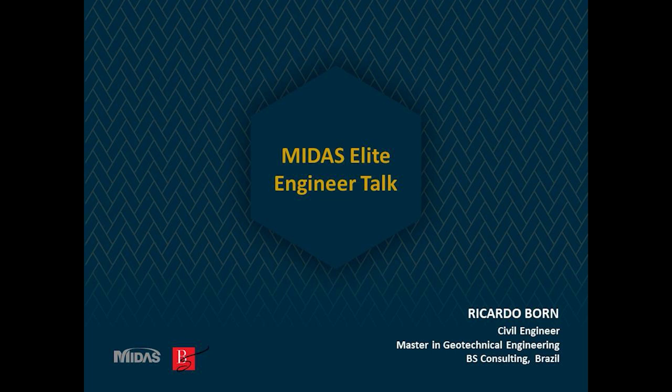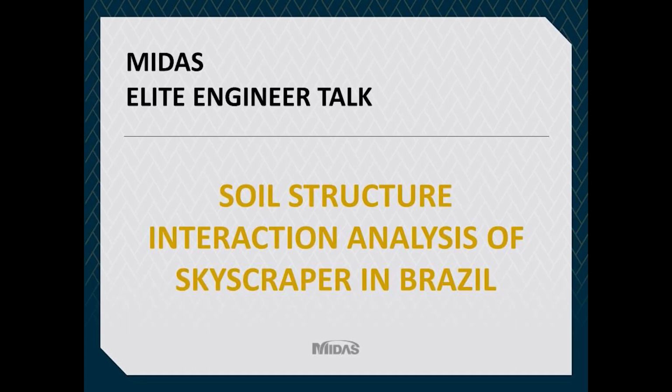So, along with a platform that enables this modeling, the soil properties might be modeled with the use of soil constitutive models. And MIDAS GTS NX allows this analysis to be done with all those prerequisites. So, this case presents a soil structure interaction of a skyscraper in Brazil.